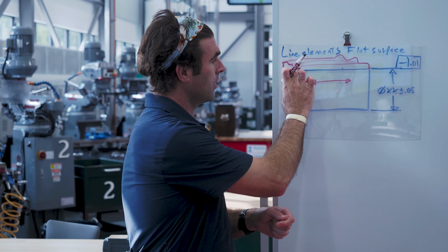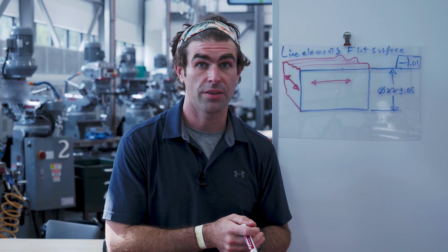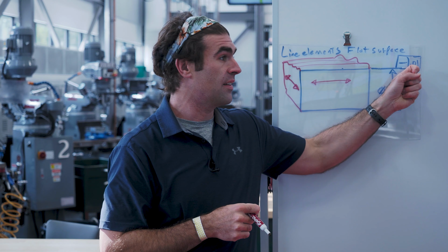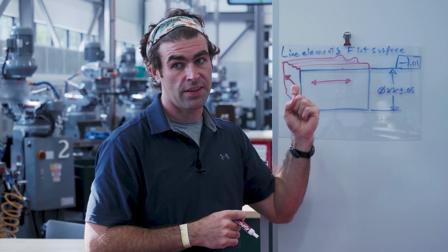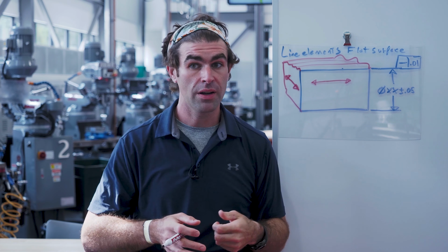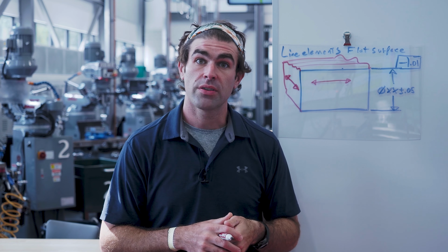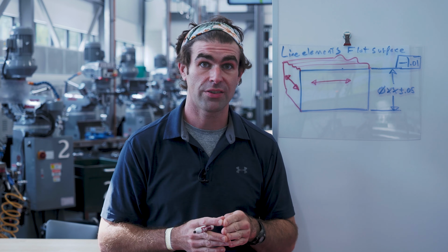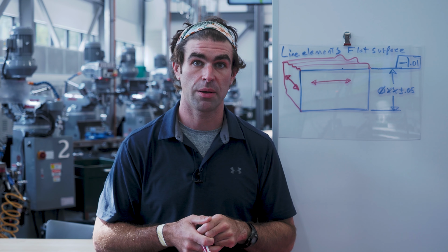Now, it is possible, say this had a right view, right? So you're showing this in projection. You could have a totally different straightness tolerance on it. So you could say 100 thou total tolerance. You got 10 thou going this way, and a separate straightness tolerance saying 10 thou going the other way, or 5 thou, or whatever. There can be combinations, but you typically wouldn't have 2 straightness tolerances going in different perpendicular directions, because you just use a flatness tolerance and it would accomplish the same thing.